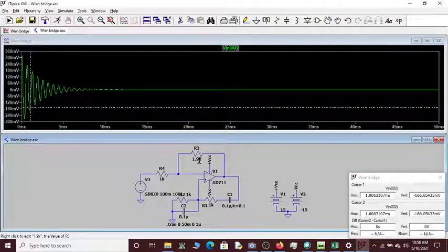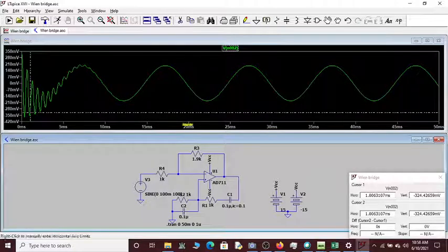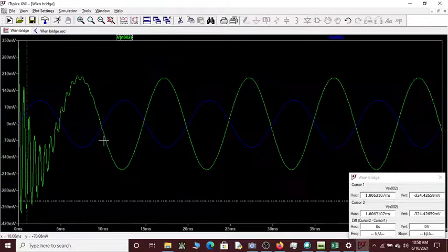Now you can see the gain is 2.9 for this. For this it becomes minus 1.9. Am I correct? Because now this is the input that you applied. This becomes like an inverting amplifier. If I run now, let me also see this input voltage. Even though initially the oscillations are dying out, can you see it is purely acting like an amplifier, where it is a stable system?